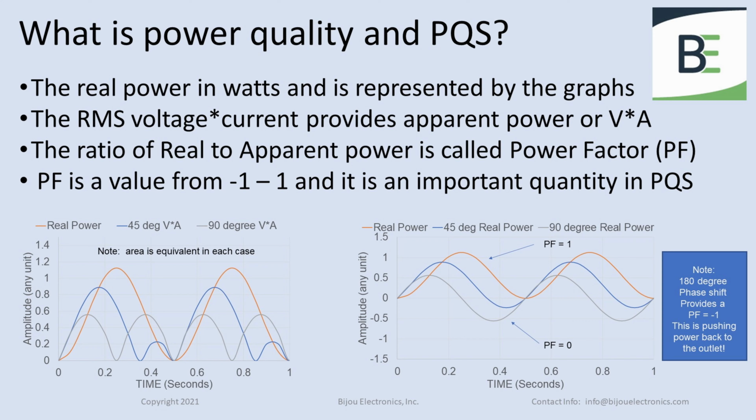In the first graph, you can see all components are positive. Current is always moving in all these cases. As you can see in the second graph, gray line, half the power is above zero and half is below. When you average these values, zero real power is consumed. To capture this current that is still flowing in the system, additional terms are used. Apparent power and reactive power combined with real power make up the metrics used to characterize power in AC systems.